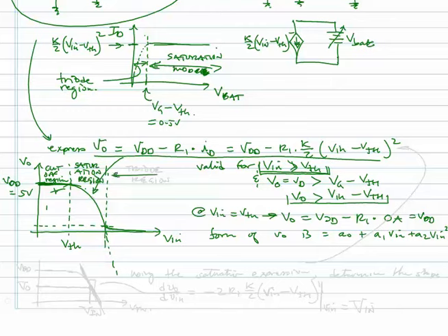And up here is what we call the triode region. Remember, what I'm drawing here is the DC transfer characteristic of the inverter. With what you have so far, if you knew the parameters of the MOSFET, the K and the V threshold, you could predict all of this. You could predict things in the cutoff and in the saturation region. You wouldn't be able to describe the triode region at this point, but at least the saturation region, and most importantly, saturation region.